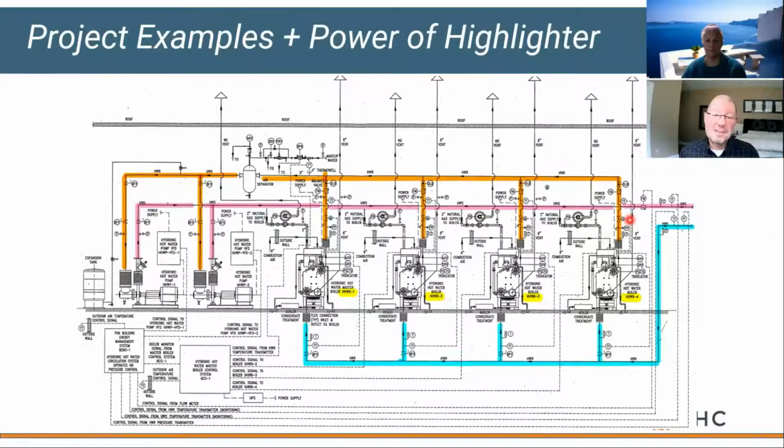Now the next question is, do I have reverse return? Well, which boiler is getting hit with cold water first? Well, that's boiler number 4. Which one's the last one to be returned to my system pumps? This one is traveling way over here, and then boom, it hits my system pumps. So the first one served with cold water is boiler 4, and it's the last one returned, okay? Really good indication of reverse return.